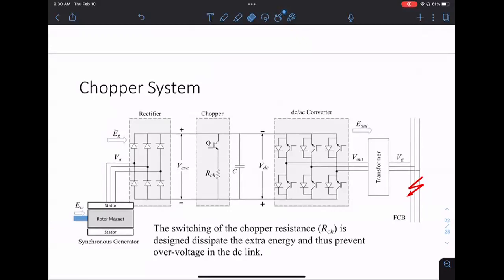Large volume of DC. Right? So what you basically want to create, the thing coming out here, is never perfectly DC. This capacitor is smoothing that. The larger the capacitor, the better the voltage looks. An infinite capacitor holds the voltage exactly at a value, so the larger it is, the more constant the voltage is. Without this capacitor, this may not function. It sort of holds everything together.